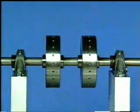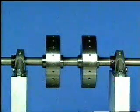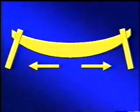A rotor which is bowed between the bearings actually has an unbalanced condition, but exerts axial force on the bearings. The bend causes one side of the rotor to be longer than the other, forcing the bearings out during part of the rotation and lets them flex in for part of the rotation. This makes it appear as if the ends of the shaft are moving in opposite directions, while for a straight shaft, the ends are moving together.